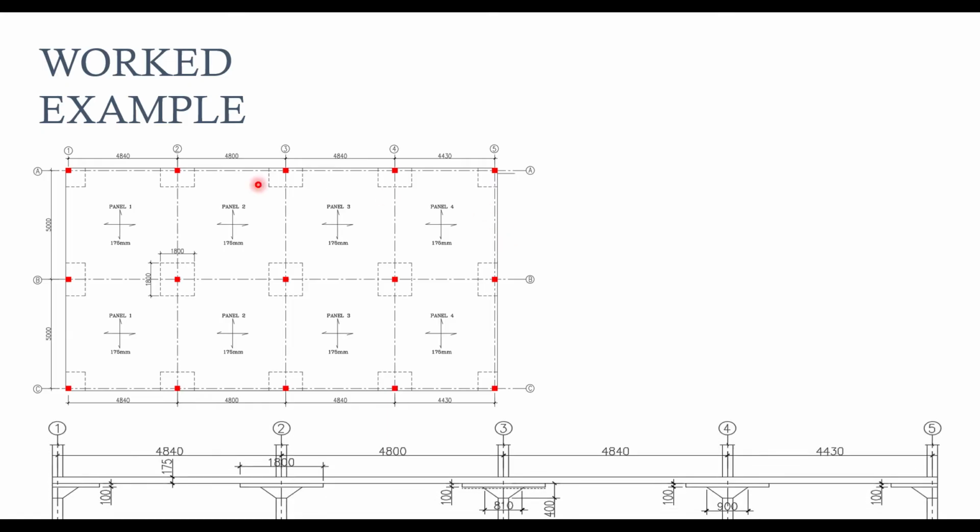So when we cut a section across grid line B on the plan view, we are going to be having this. Some of the things that we can detect from here is that our slab thickness is 175 based on this dimension. In our previous video, I explained that the minimum flat slab thickness according to BS 8110 is 125.